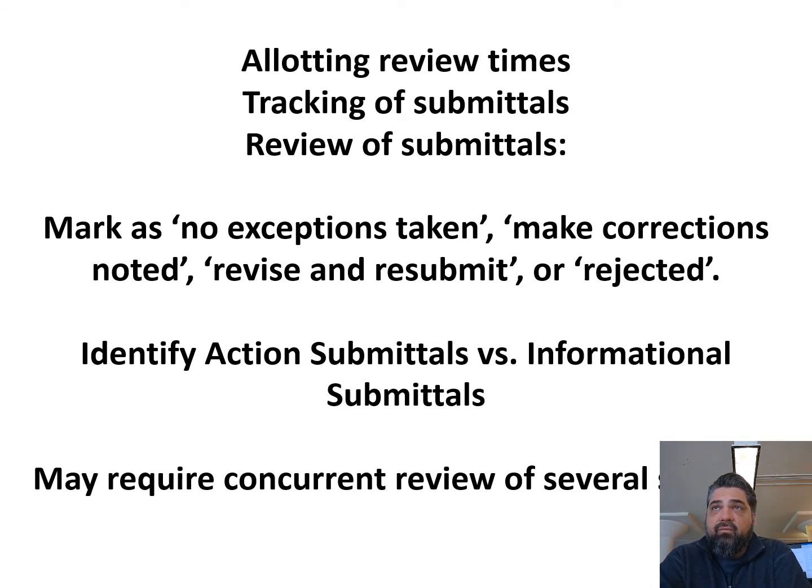And then the last item, rejection, is simply, it's maybe a material that is not approved or allowed by the contract, or it's the wrong system, or the contractor hasn't reviewed it yet, and so you just simply reject it.